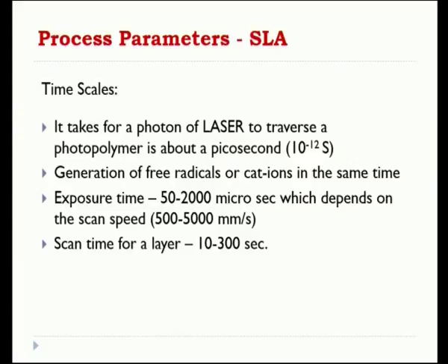But still we are always saying there is a problem with time. Is there any other alternative way to build up the speed of the material, the speed of the equipment, or the speed of product development? One quite common way is increasing the layer thickness, but we cannot go beyond a particular limit, because the layer may curl, or it can leave a wavy output, and many other problems. Is there any other way you think we can achieve this?